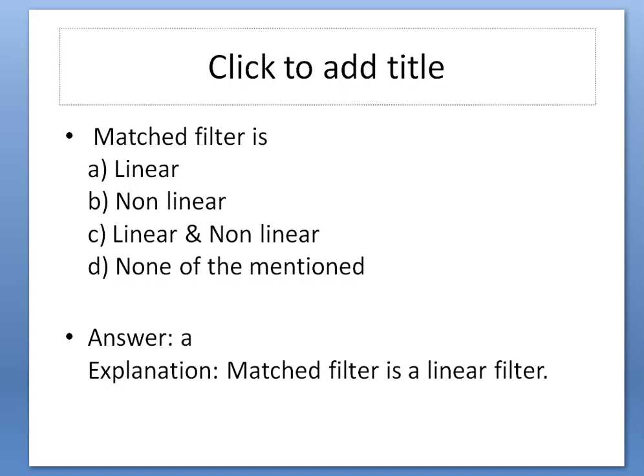Then we calculated eta, the efficiency parameter, based upon the effective area and aperture area of the antenna, and finalized the value of gain. If a radiator is isotropic, the gain is equal to unity. If the antenna structure changes, the efficiency also changes from 0.55 to 0.75 depending upon the shape.